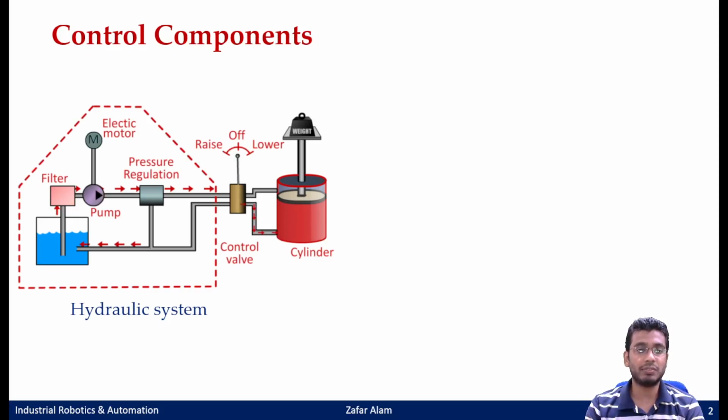The control elements are used to divert the fluid to a particular port to do your intended function. For example, the control element is responsible for either diverting the fluid to the lower end of the cylinder, which causes the extension of the cylinder, and if the fluid is diverted to the top section of the cylinder, then the cylinder is retracted back.